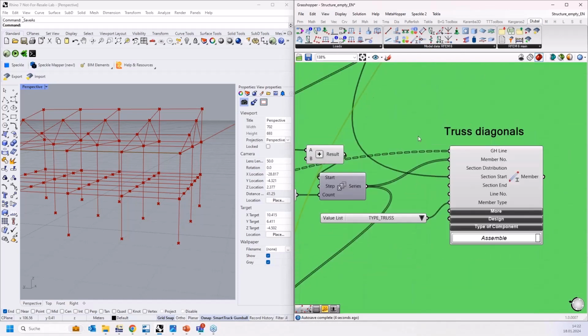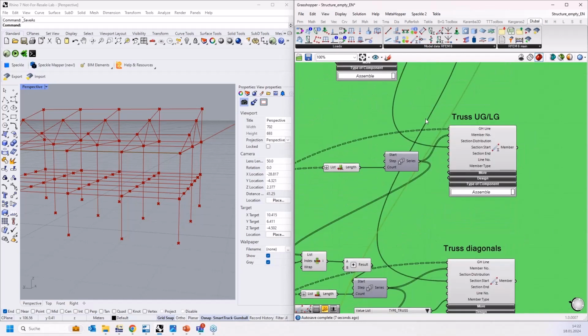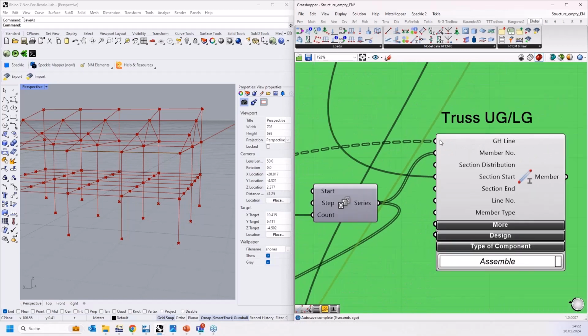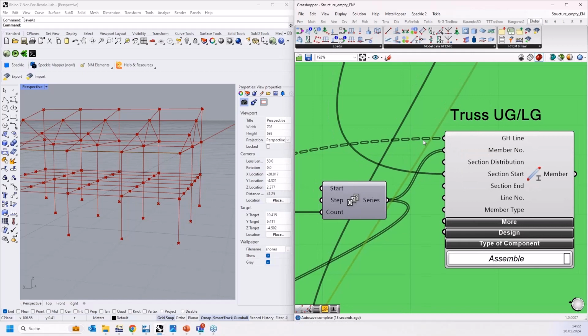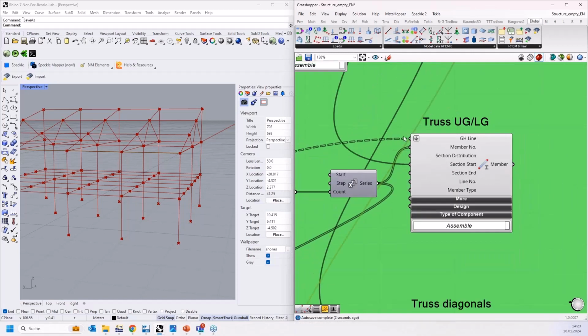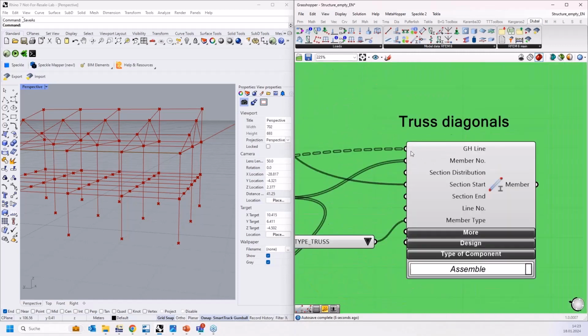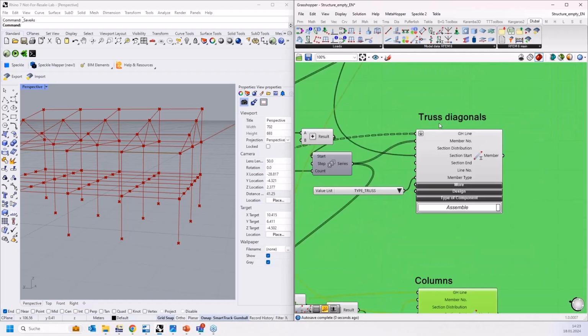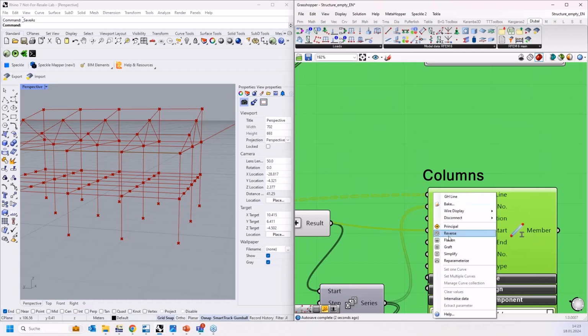And what I forgot, I just noticed it in all the member components: we have to be careful when we are combining tree-like structures with lists. That's a bit tricky part. In my case, I will simply flatten the incoming tree structure to get a list, and then it will combine both lists with each other. That is something I have to do.